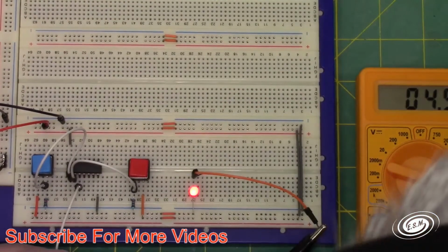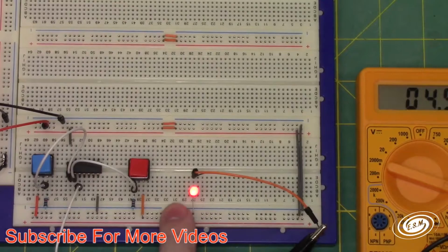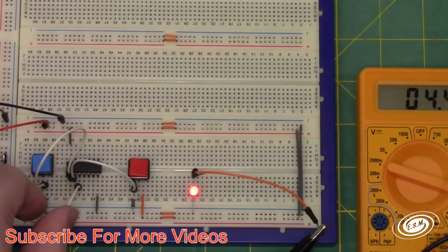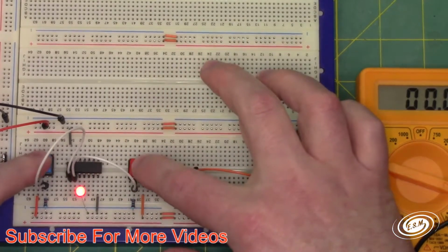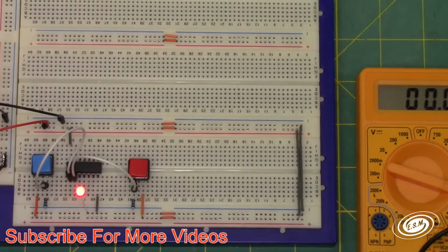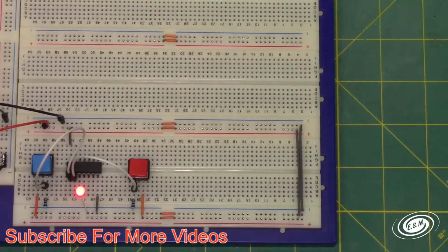Okay, so 4 milliamps, so technically you don't need a resistor for this LED coming from one of these CMOS chips. In all theory, I could take this and plug it in just like that, and then I can control that. So it was 4 milliamps, which is way under the 20 milliamps of an LED. I don't know if I would run it like that forever, but that's the amperage that the chip runs at.